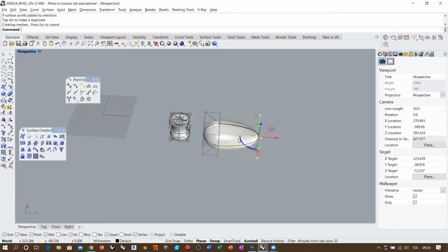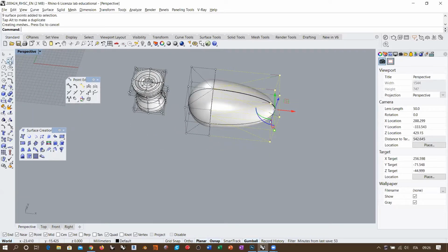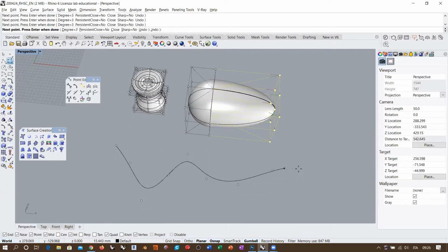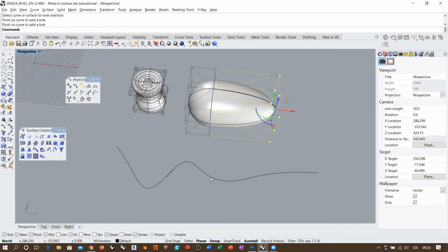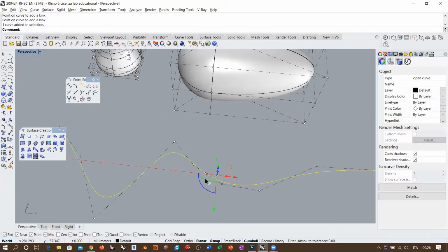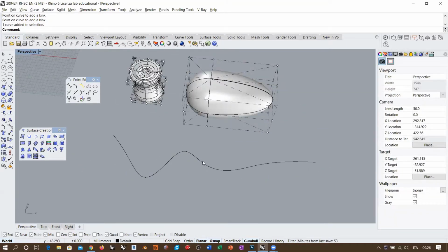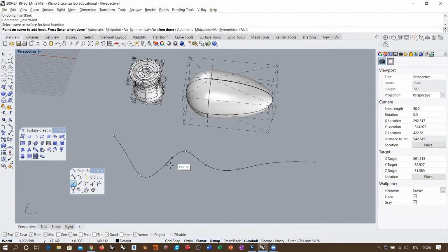So remember when we saw the freeform curve like this, and we decided to add a kink to this curve like here. Okay, so we know there is a discontinuity here, but if we don't change the, oh sorry, let me do this in a more visible way. Just give me a second. So let me see where the knots are. Okay, they are here. I'm going to add a kink here, which is a safe area. Okay, so add kink here, like here.